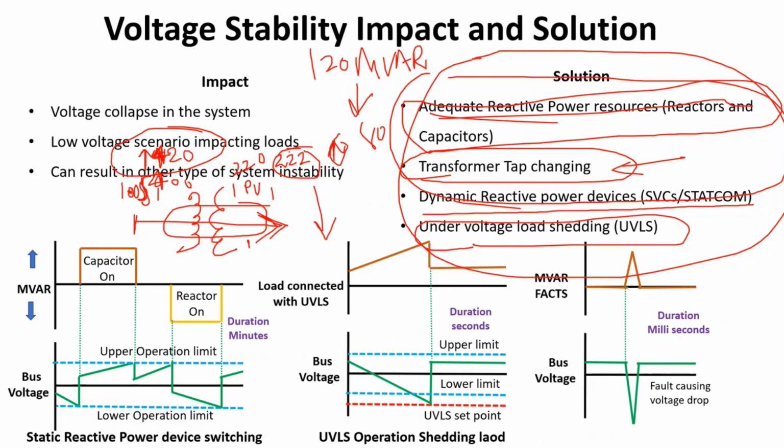But whether you are able to completely dictate everything you tell the generator to do, are they doing that? Not completely possible. They have a lot of issues. If you ask them to absorb more reactive power because of high voltages, they will tell you that on the LV side the voltages will go so low, given my GT type, that I will face a lot of problems with my auxiliary system and auxiliary loads. So they will face a lot of challenges during any voltage fluctuation.